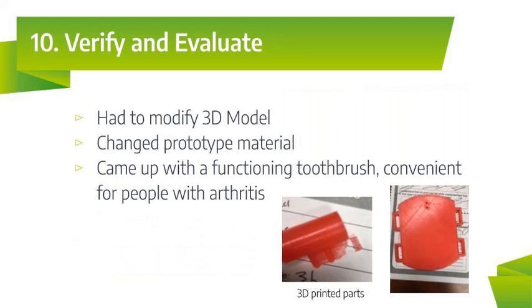After the first prototype, we realized that there were some flaws. First of all, our 3D printed connector piece initially came out deformed due to the limitations of the model that we designed. In order to fix this, we reprinted and subsequently machined the parts to specification. Another problem we encountered was our original intent to make the bendable portion of the brush out of low-density polyethylene for flexibility. Due to the non-workable nature of commonly available forms of this plastic, the hot glue stick was used in its place in the final prototype.